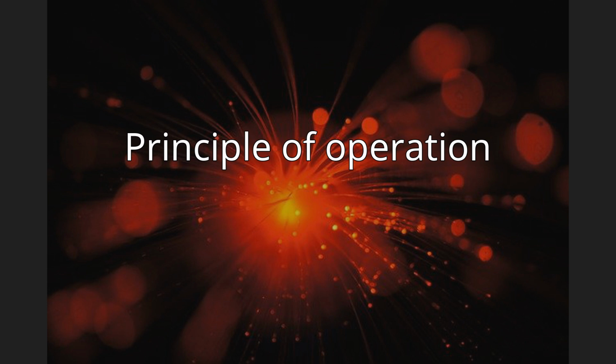An optical fiber is a cylindrical dielectric waveguide, a non-conducting waveguide that transmits light along its axis through the process of total internal reflection. The fiber consists of a core surrounded by a cladding layer, both of which are made of dielectric materials. To confine the optical signal in the core, the refractive index of the core must be greater than that of the cladding. The boundary between the core and cladding may either be abrupt, in step index fiber, or gradual, in graded index fiber. Light can be fed into optical fibers using lasers or LEDs.